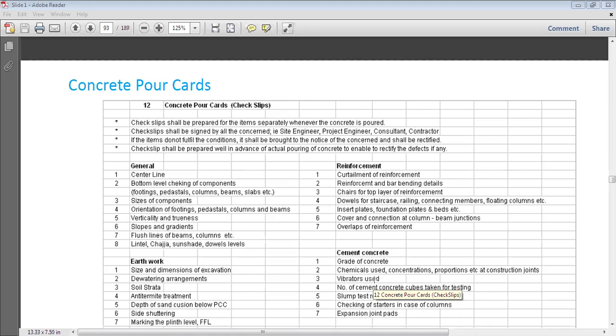You know the basic process of the slump cone test. It's a cone of height 30 centimeter, top diameter is 10 and bottom diameter is 20 centimeter. Then you pour your concrete into that cone, and then you lift the cone. So you measure what kind of failure has occurred. Total height we know is 30 centimeter minus whatever the slump which occurs. Based on it, you can suggest the workability of the concrete, whether it's highly workable, low workable, or good workable concrete.